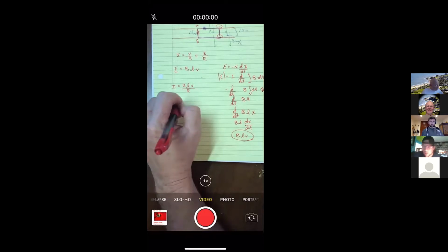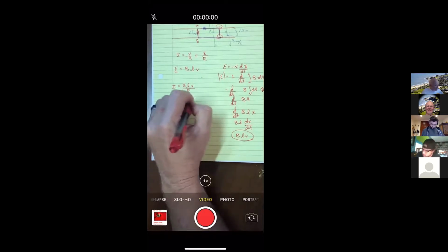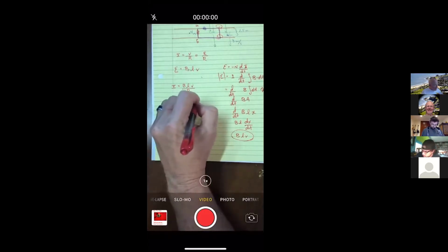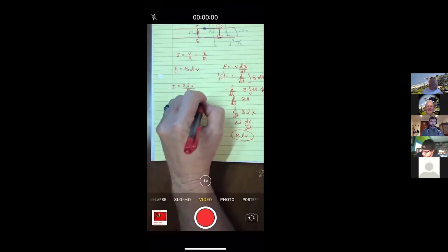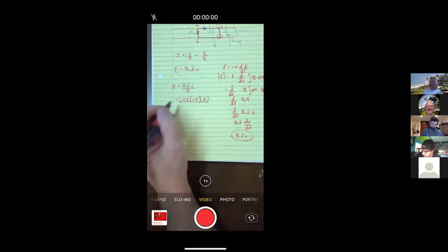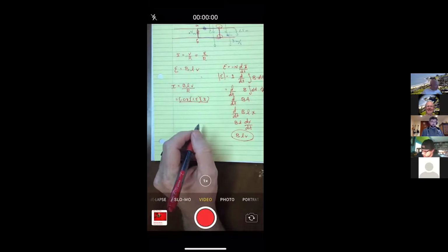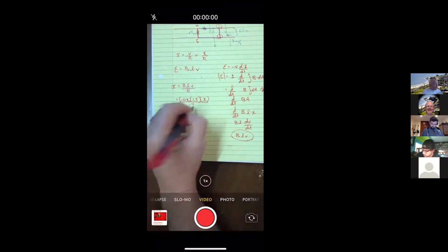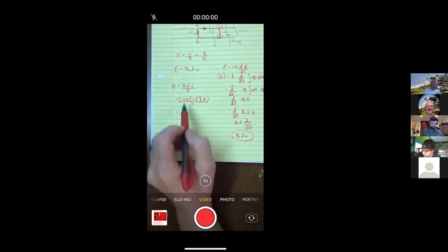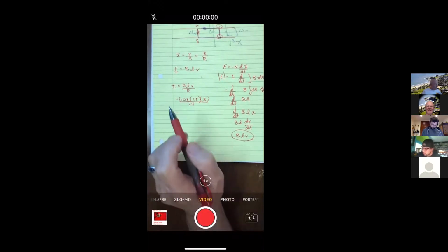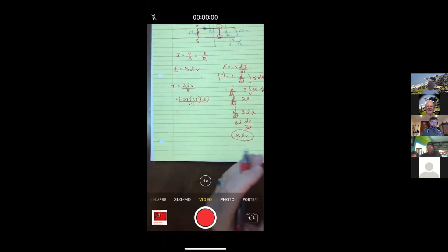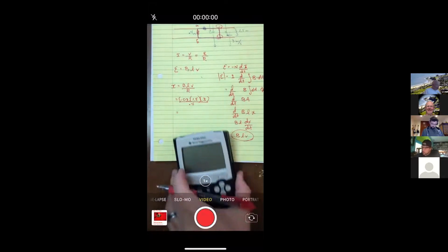So they said the field was 0.08, okay. They said the length of the axle was 1.5 meters. They said it was moving at 3 meters per second. And the resistance is 0.4. Now, it's going to give me more current than I thought, but this is a huge field. This would not be like a real train moving in the Earth's magnetic field. That's a really good size field.